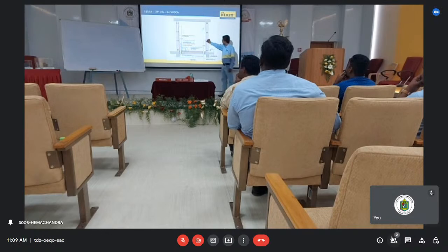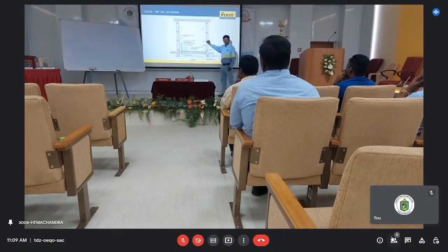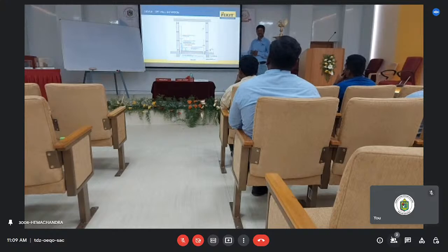So panel structures. Here this entire structure will be a panel, precast structure. So what do we do? First we apply polyurethane sealants in the joints. All the joints will be taken care of. Before that, during the construction activity itself, the precast contractor will do the grouting. They will fill all the gaps. Only the surface area gaps we will fill with polyurethane sealant.